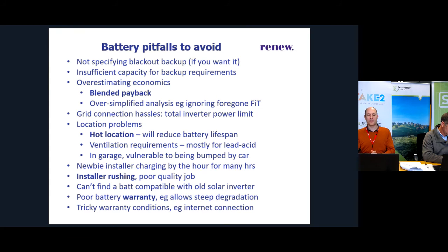All looks good. What they've done is roll together the economic benefits of the solar panels as well as adding the battery into the system. So if you ask them for a quote for just the solar system without the battery, you might find a payback of 4 years, and the upfront cost is a lot lower. Your annual bill saving won't be quite as much without the battery. So ask for a quote both with and without a battery, so you have a clear picture of both options.